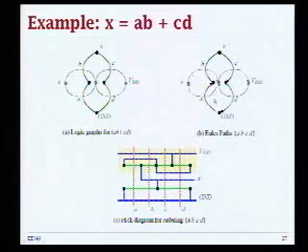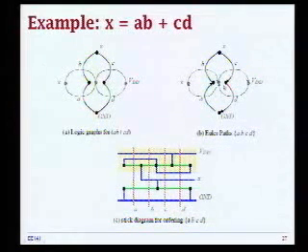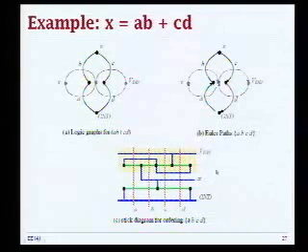And it's not quite visible in this slide. So you basically just go in the pull down. You have vertical pull down. So you have A, you will go B, C, and D. And then for the pull up, you again go A, start from here actually, A, B, C, D. And then you have this nicely lined diffusion that is continuous for both PMOS and NMOS. You can just route vertical stripes. And if you create this stick diagram, throw it into a tool, automatic layout.